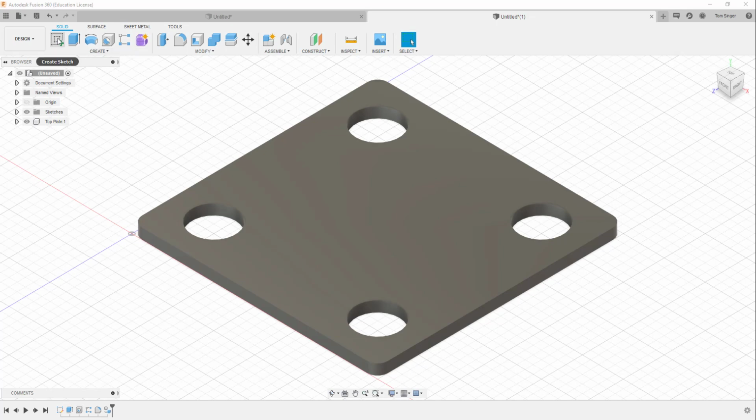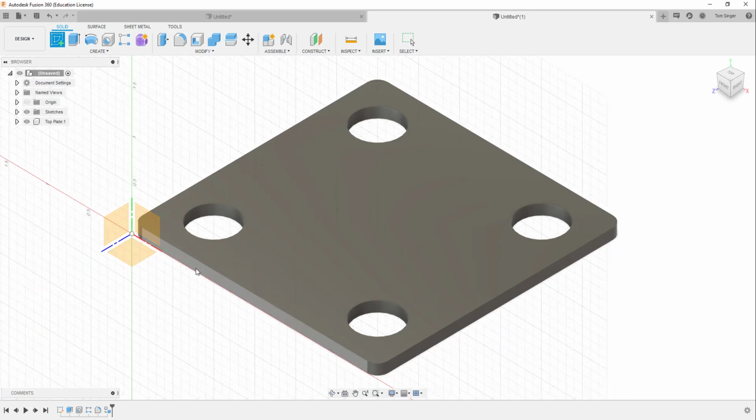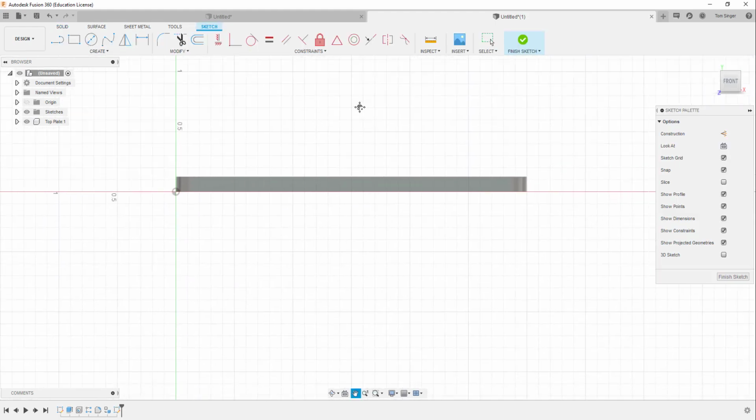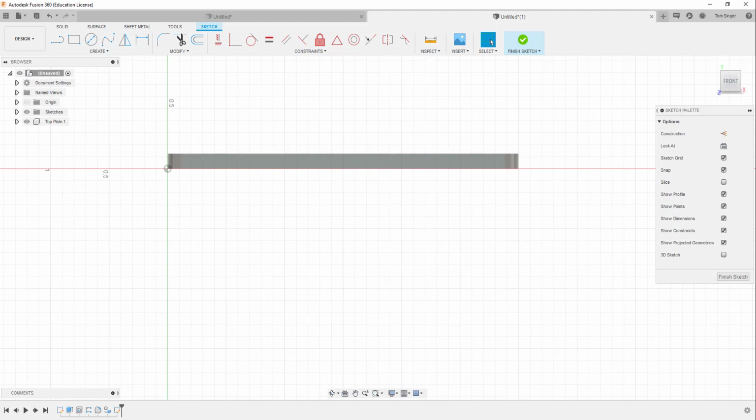We're now going to create a new body, and that new body is going to be based on the edge of our part. So now we're looking at the edge of the part, and with this particular drawing, we have to lay out some construction lines, and the construction lines help us position where we're going to create the tangent arcs in the object. So initially I'm going to draw a line, and it's going to be in the center here, and we can find the midpoint, and I'm just going to continue to draw up, left mouse click straight down, and right mouse click and choose OK.